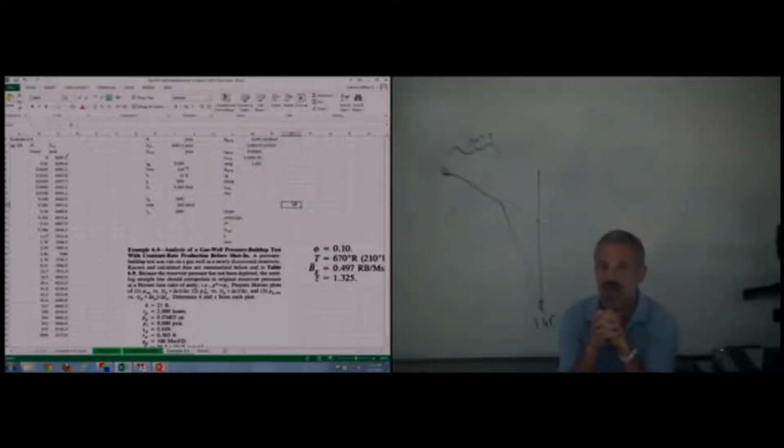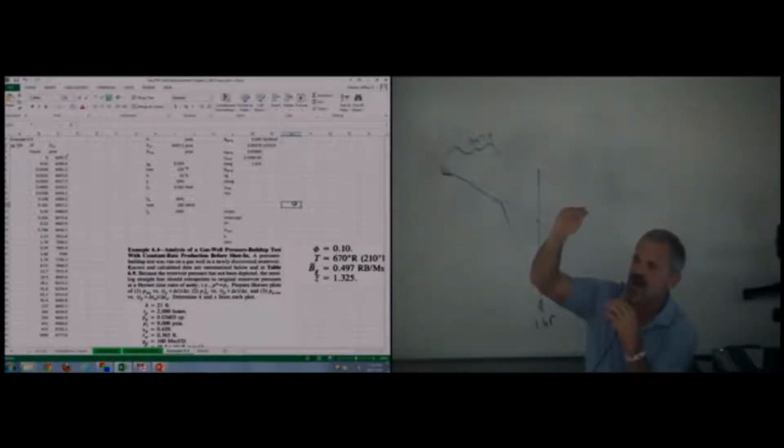Because if we're going to build a numerical simulator model to tell us what this reservoir is going to do, obviously permeability is always the most important reservoir characteristic there is. But initial pressure is very important too. Because in an oil reservoir, like the ones we were drilling in Wyoming, we want to know how far above saturation pressure we were, to know how much production we'd get before we went into the phase envelope and had a big increase in GOR.